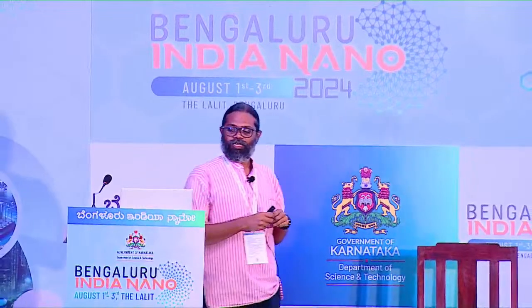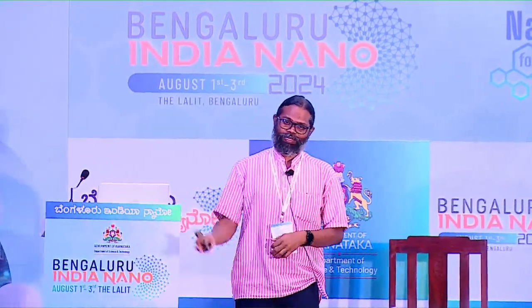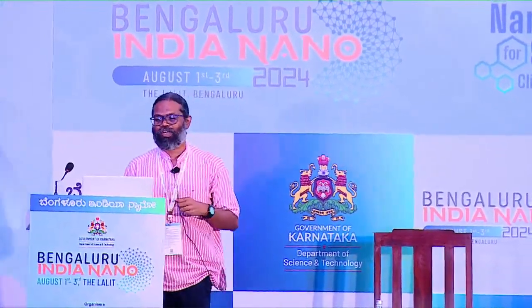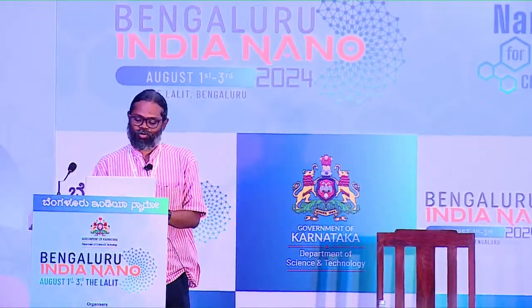And this isolation is provided by the best insulator that we can get from silicon, which is silicon dioxide, okay? So silica, right, where you get sand. Sand is nothing but silica, and refined of that is silicon, right? So you can use silicon dioxide, which is a very good insulator. It will not conduct electricity, right? We can use that. And that particular process is called the shallow trench isolation process.